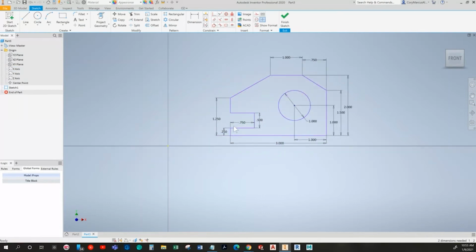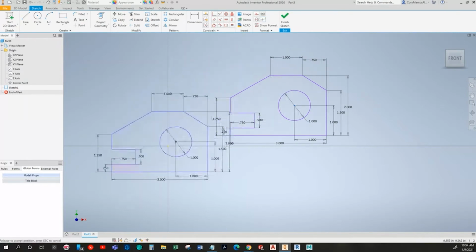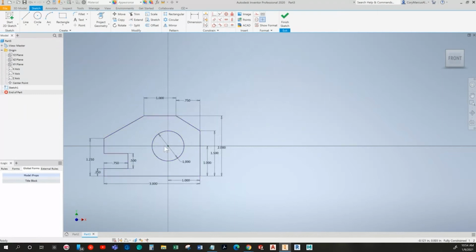Starting out, it's fine just to do a corner or something. Just have a part of the sketch touching this point. Later on you'll have parts centered upon it. But for now, I'm just going to choose this circle, and I'm going to choose to make it touch that. So if you notice now, fully constrained, the lines went black. We have located everything for the sketch.